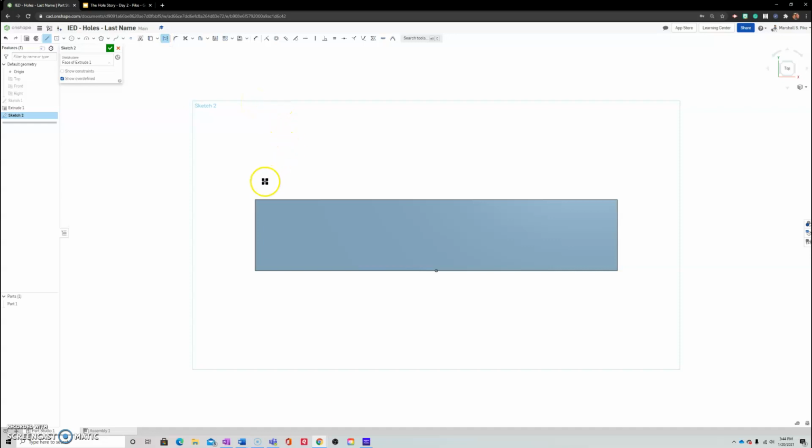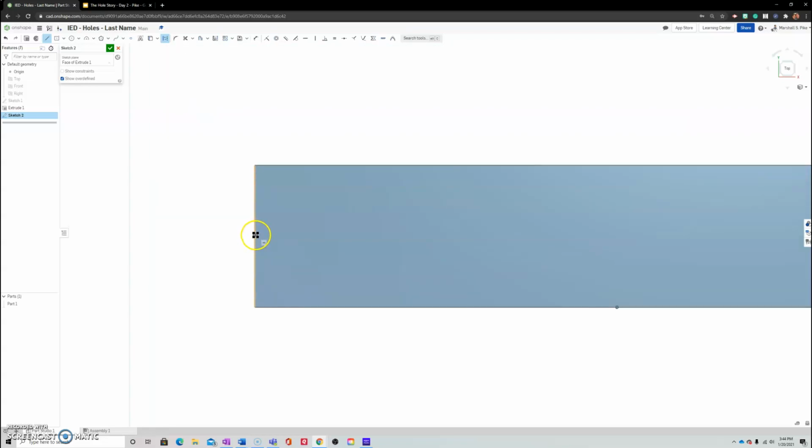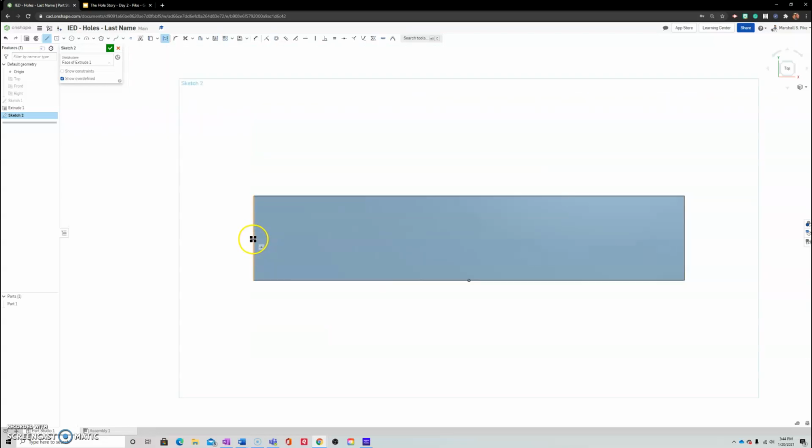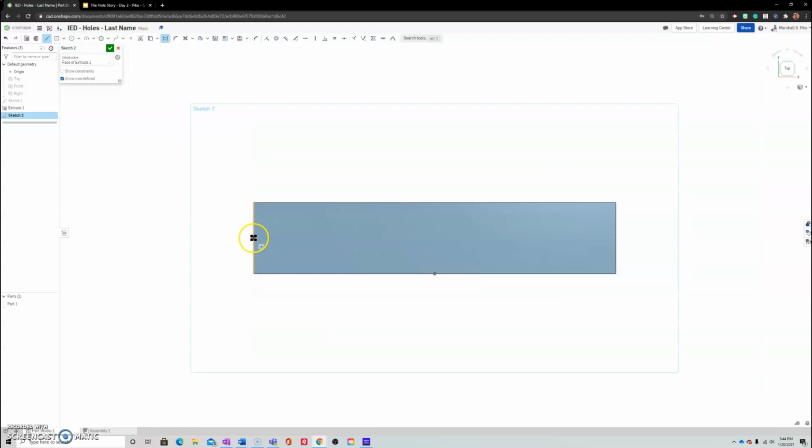And the reason for that is the construction line is used for dimensioning or location purposes, points of reference, but it doesn't necessarily come with us in our 3-dimensional world. So now I'm ready to add my line, and since this block is all 2 inches if I hover and drag, when I get to the midpoint of that line, it'll grab the grip as a little rectangle. And I can certainly put it on there and dimension it later, but since I can easily grab the grips, I'll just grab the grips and draw my construction line.